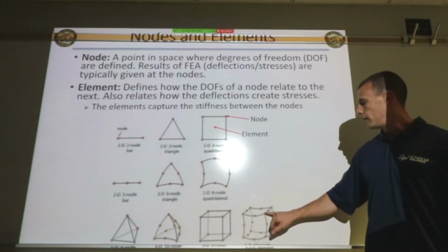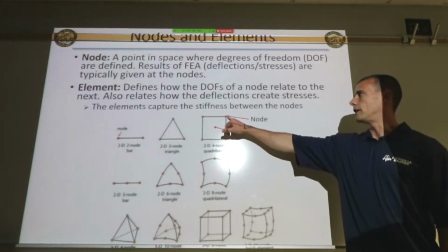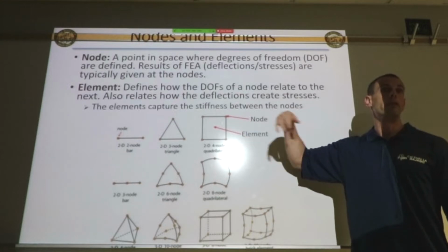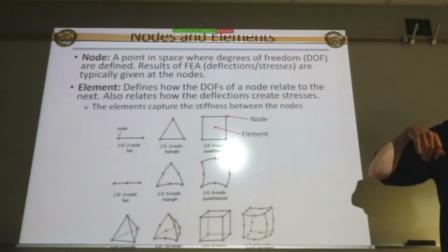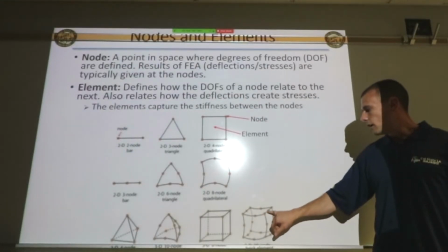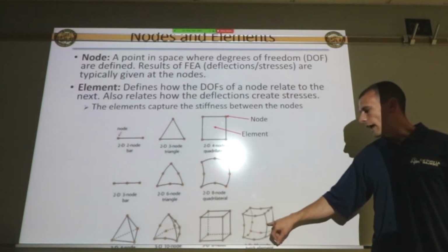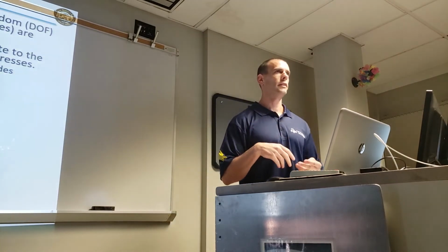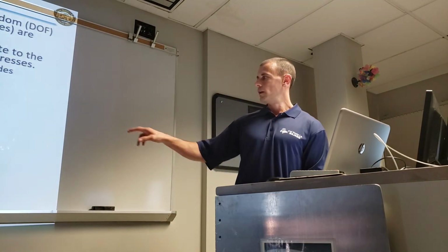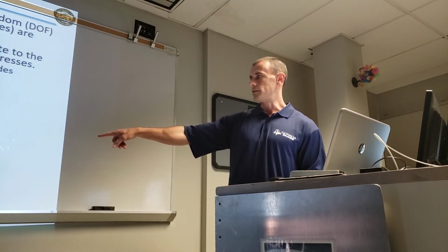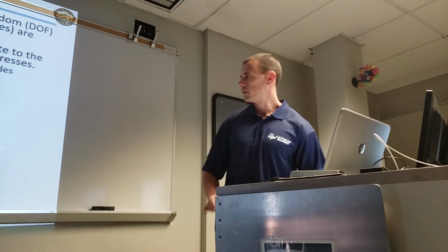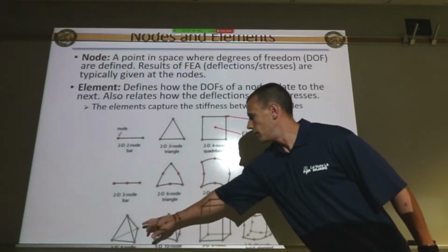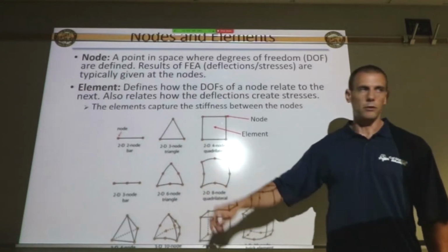The difference here, and we'll talk about this soon, is that it linearly interpolates between the two nodes, right? There are actually other elements where you create the element and it has subnodes in between to get a polynomial instead of a linear fit, basically, which is less common to see. It's more computer time. So you typically see this one, and then these simple 2D ones.